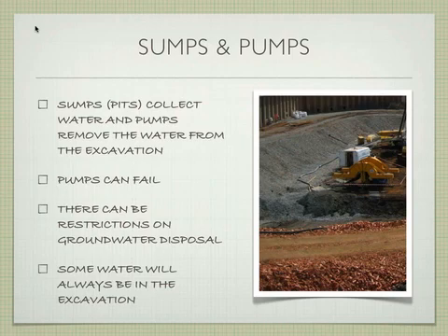Sometimes there's toxins. Say you were doing this in Alameda, on the Naval Air Station. That whole land you're not even allowed to dig on because it's so full of toxins. So that's a big problem. If you suck the water out, you've got all this toxic water. What are you going to do with it? So that can be a problem. The other thing is there's always going to be water in those pits. So you're always going to have some water on the excavation site. So what happens if you need to work where the sump pit is? That can be problematic.